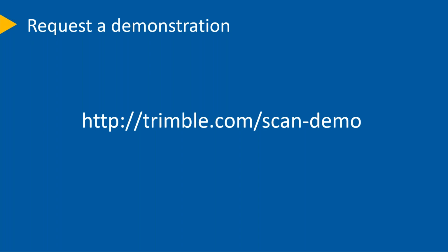TBC or Trimble RealWorks, which is better? So that's kind of a funny one. Trimble RealWorks will have a lot more inspection and modeling capabilities if you're trying to do this analysis or BIM workflows. It's been around for a long time and has a lot of tools very specific to point clouds. TBC is a very strong geospatial software, so very good at putting data together in coordinates.